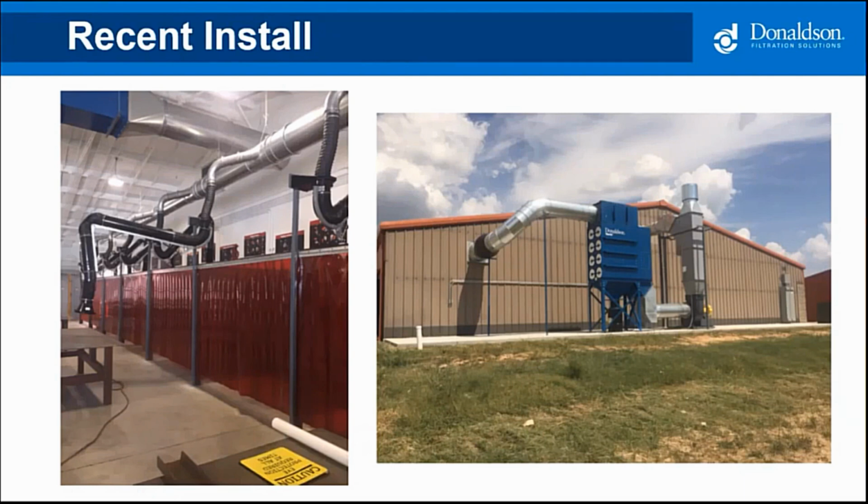But we still have to take precautions, and this is a passive device that takes the ember through a tortuous path, breaking it open. As it's broken open, that inner core where the heat is exposed to oxygen, and it will extinguish. So then the air goes through the collector, down through the clean air plenum to the blower.